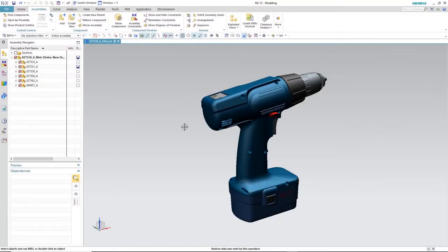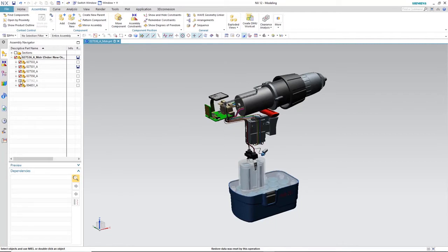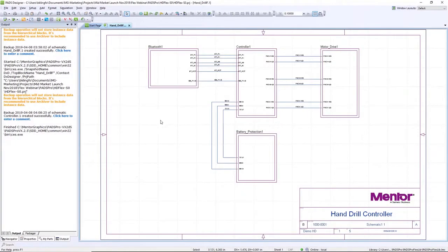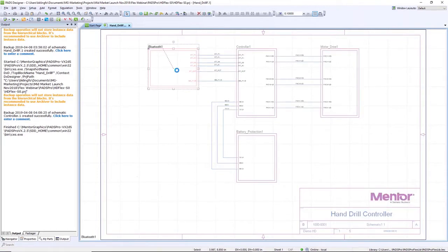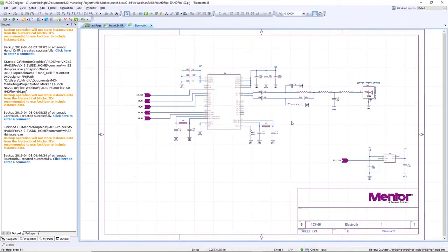In our example today, we're going to create a small drill with a rugged LCD display and Bluetooth connectivity. The LCD will take advantage of cost-saving flex technology by removing two connectors and cable assembly. The Bluetooth board will also be attached via a flex interconnect. We haven't created the PCB yet, so we're going to start from the schematic. We'll review the new circuitry that we have added, which in this case is the Bluetooth circuit. We'll then activate the Start PCB function from the schematic tool.